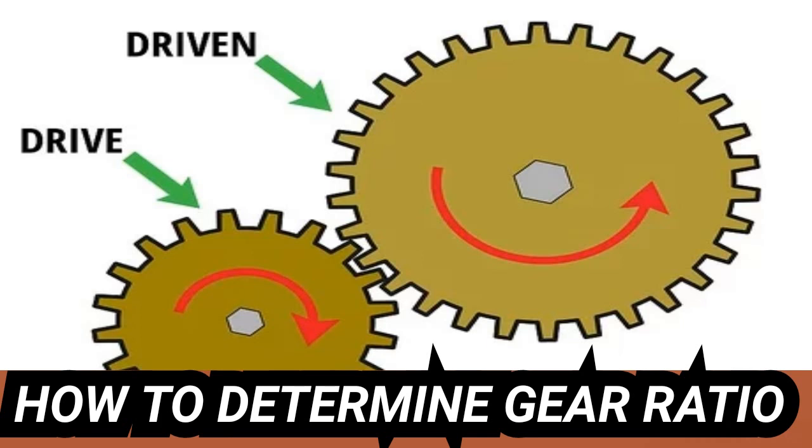In our example, the intermediate gear ratios are 27/10 equals 2.7 and 30/20 equals 1.5. Note that neither of these are equal to the gear ratio for the entire train, 4.3. However, note also that 27/10 times 30/20 equals 4.3. In general, the intermediate gear ratios of a gear train will multiply together to equal the overall gear ratio.